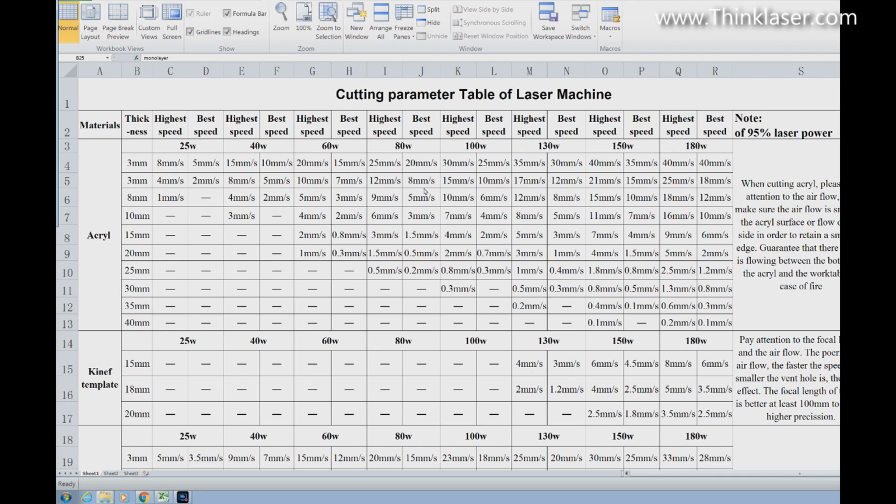Well, I think we've already established that 95% laser power is a killer. It's not going to do your tube any good at all. On my machine at 67% power, I should be overdriving the tube and seriously shortening its life. That immediately brings into question the validity of all these figures. Because if they were done at 95% power in the factory on a machine which on that particular day produced those numbers, that's fine. That's fact. But they're not fact for your machine or my machine.